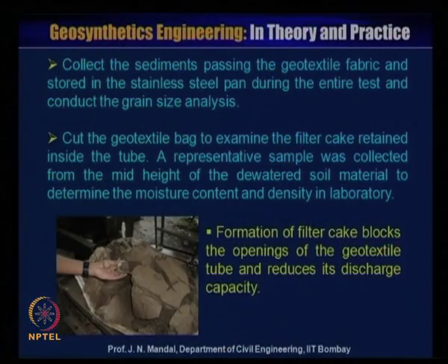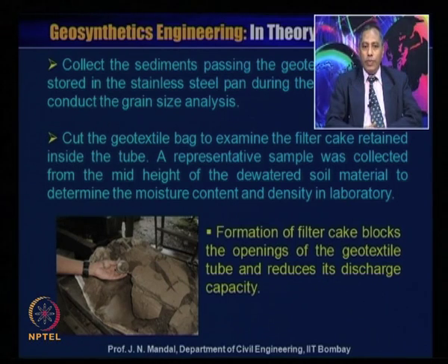So, now collect the sediment passing the geotextile fabric and store it in a stainless steel pan during the entire test, and conduct the grain size analysis. Cut the geotextile bag to examine the filter cake retained inside the tube.